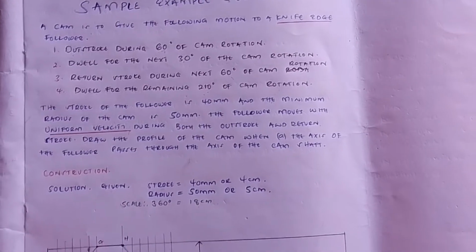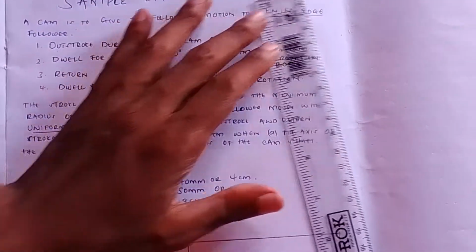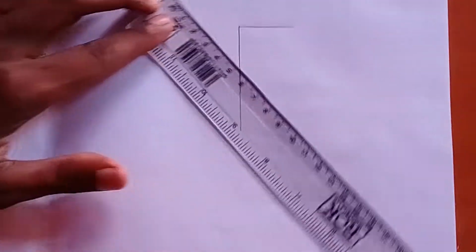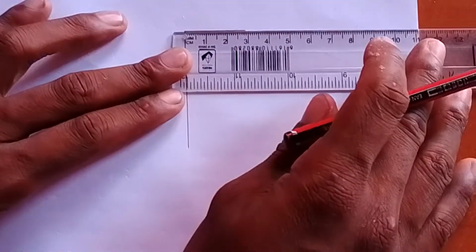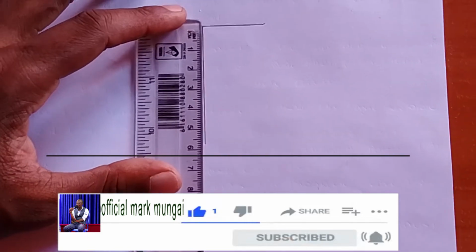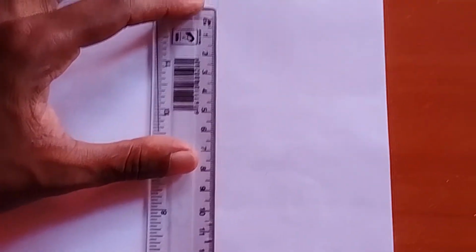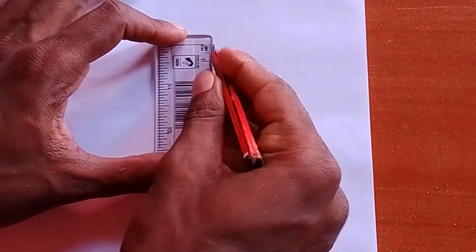The knife edge follower is the very first thing that you construct when you want to construct a cam profile. So from this point again, you can use the width of the cam. Let it be 3 centimeters, like I have used here. And you can use the height as 6 centimeters, like this. Also here can be 6 centimeters, like that.